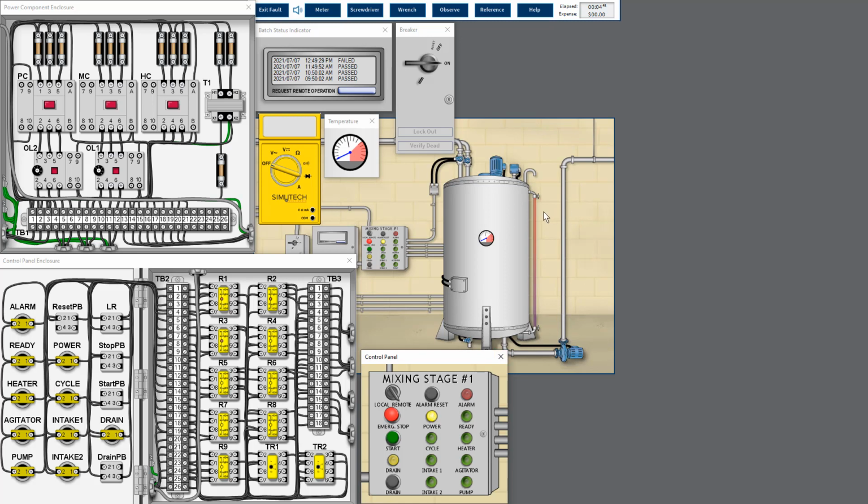Okay, and I also observed that there's water inside the side glass, and the water is actually at the maximum level. So I try to drain the water and run the process, because I don't see any other anomaly from the circuit or the external device. After finishing draining out the water, I will run the process and observe for any anomaly. Okay, run the process.